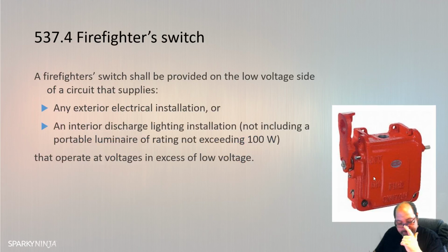Firefighter switch. BS EN 60947-3. It shall be provided in low voltage circuits supplying outdoor lighting installations operating at a voltage in excess of low voltage, such as neon lighting and things like that. Indoor discharge lighting, again with similar voltages.